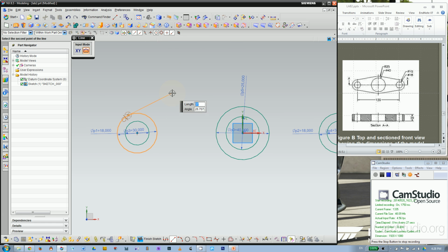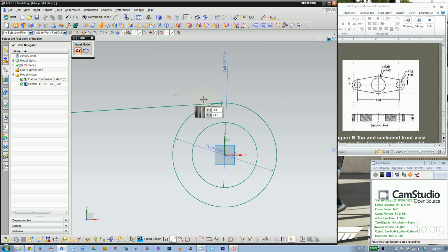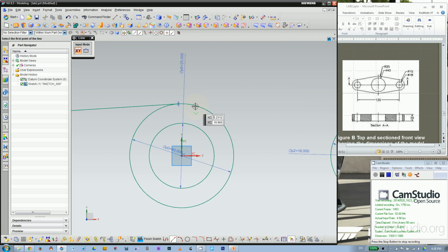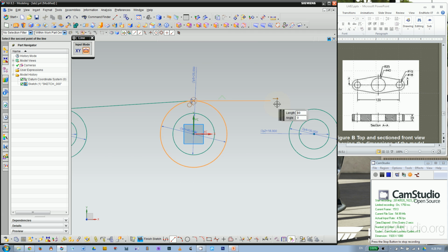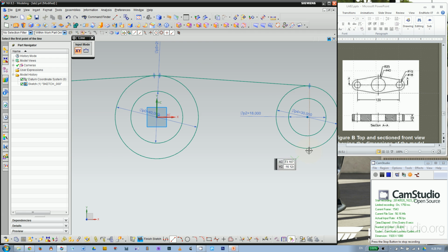Okay, so a little bit outside, click. Okay, and now it's tangent. That's good. So I'm gonna move here, and I see that's tangent. That's also good. And wait for this icon, the same as this, point on curve. Click. Well, that quick selection window is because I hovered on the position too long. So I guess that's the third way. Just wait and see this quick pick and pick point on curve from that window. So now also here, point on curve. You can do the same for the bottom.